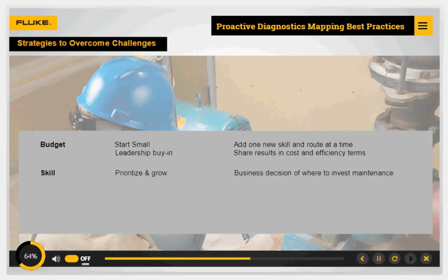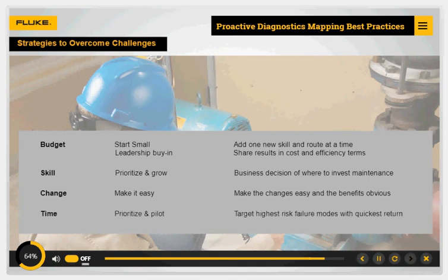If your team has good technicians, mechanics, and electricians, look into vibration, thermography, and ultrasound. Those technologies are feasible to bring in-house with some basic training and entry-level tools. When it comes to getting buy-in, start with small changes that require little extra effort, and then demonstrate how the new practices can reduce frustration and make everyone look better. No one has extra time. Start with the low-hanging fruit, such as mechanical systems that never receive vibration analysis. Run a pilot program and demonstrate the time and cost savings of proactive versus reactive maintenance.